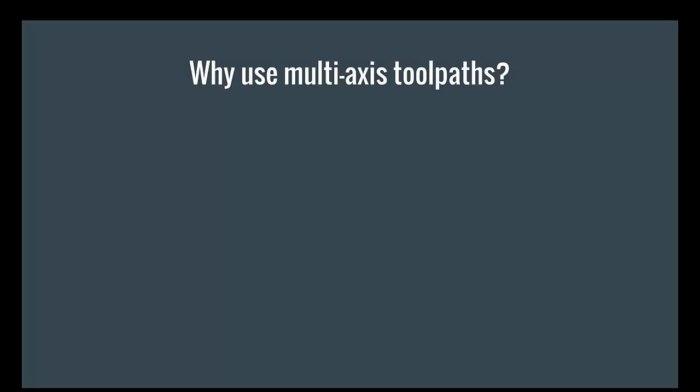Okay, so like I said, my talk today, I wanted to talk about multi-axis toolpaths. When I say multi-axis toolpaths, I'm not talking about just 3+2 machining. I mean genuine 5-axis, or maybe we'll include 4+1. Before I started using multi-axis, I found myself wondering when I should use them and why I should use them.